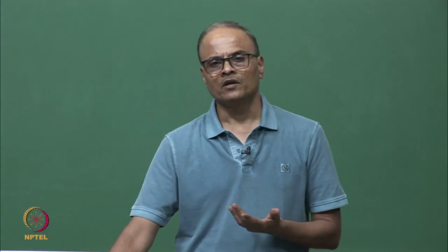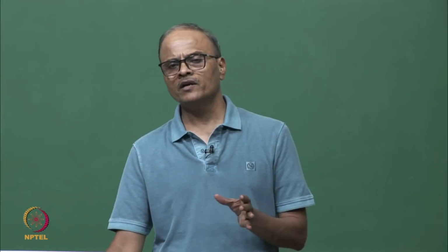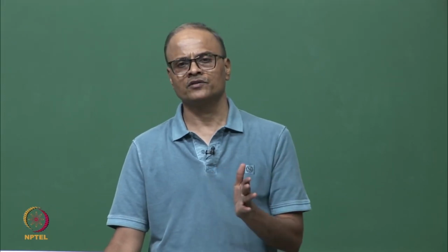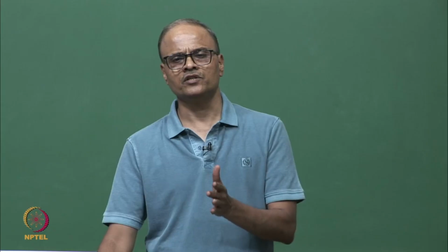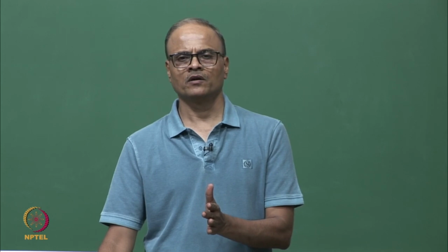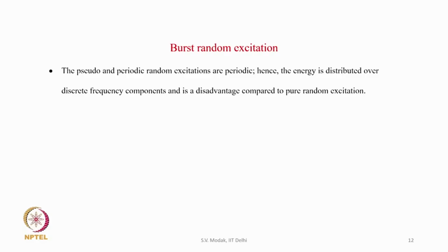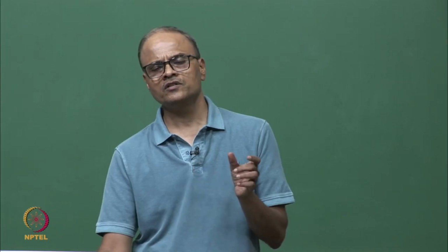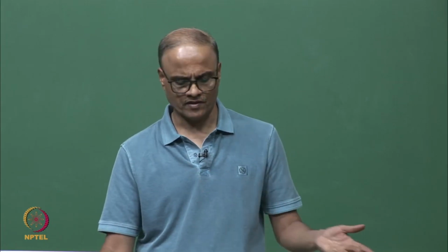We saw that these signals are synthesized by combining discrete harmonic frequency components over the frequency range of measurements. So, they do not contain energy distributed continuously over the whole frequency range of measurement. It is concentrated at discrete frequencies, but a pure random excitation signal excites the structure continuously over the whole frequency range of measurement, not only at discrete frequencies.